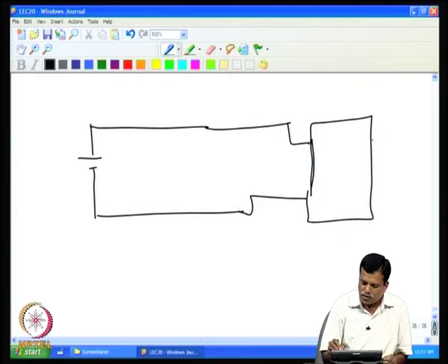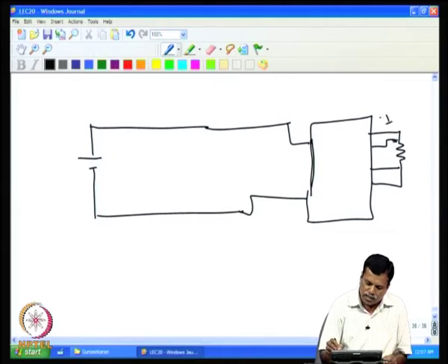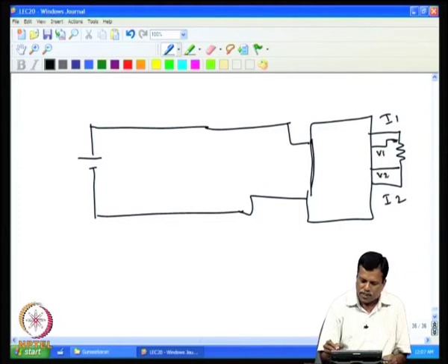And to this circuit the PRT is connected. It is a 4 wire method. So, we will have 4 points, 2 current points and 2 voltage points. So, this is I1 and I2, and the 2 voltage points are V1 and V2. So, a 4 terminal connection is made, and this is actually the current transmitter, a 4-20 milliampere current transmitter.